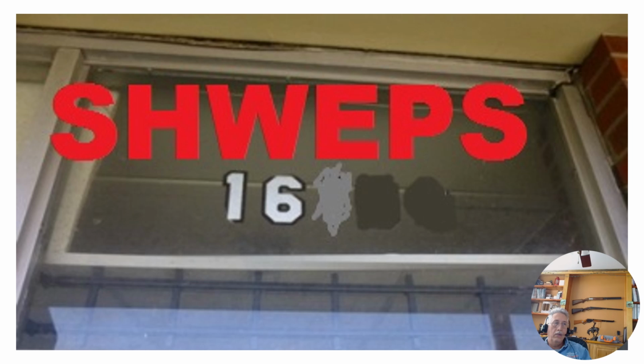So you can hear me talk about something called SHWEPS. It's just a goofy acronym I made up that actually is very helpful to me in inspecting. The first S stands for surfaces, structure. So when I'm on the outside of a building, I'm looking at the surfaces, structure. I just go through my mind, surfaces, structure. I'm looking for peeling paint, cracks in the brick or the block, any anomalies.